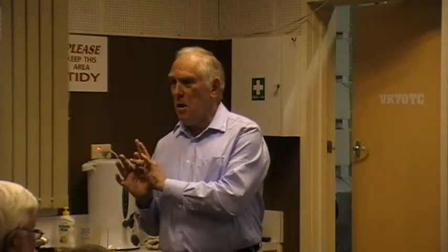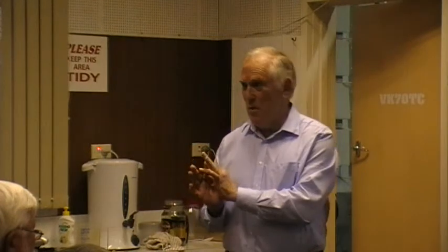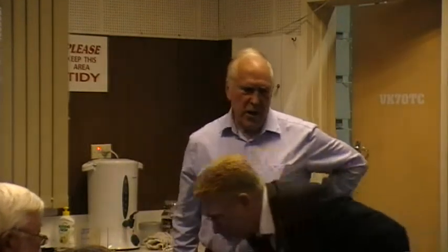I'll show you later about the beam waveguide system, but I started off by explaining to the guys we're looking for this piece of rectangular pipe coming out of the bottom of this system somewhere, the waveguide. What size is it? I mean, it was that basic, and it turns out that there were all kinds of filters and things in the way, and when we actually tried transmitting into it, the return loss was 8 dBs.